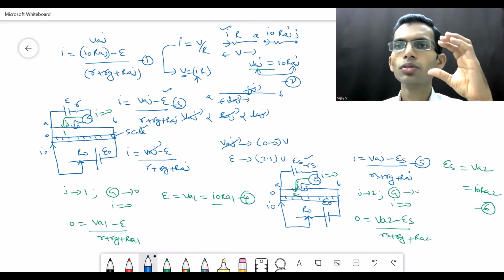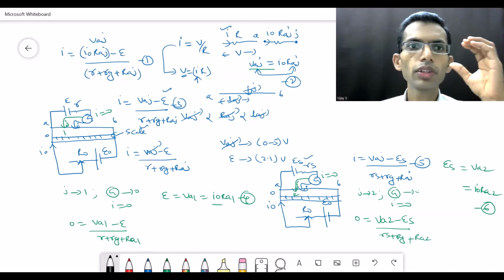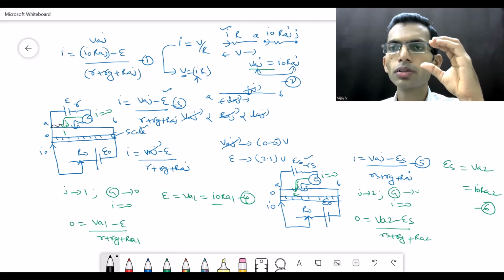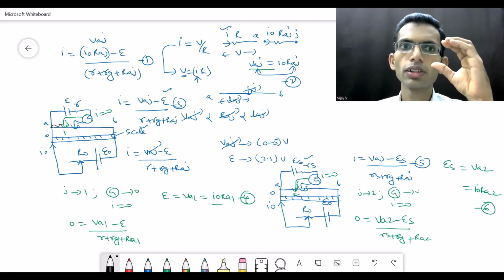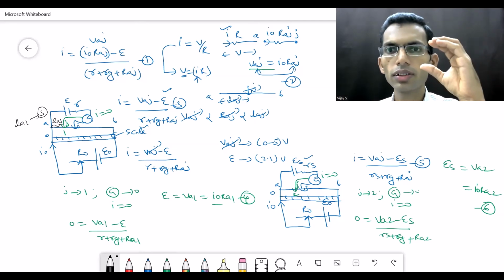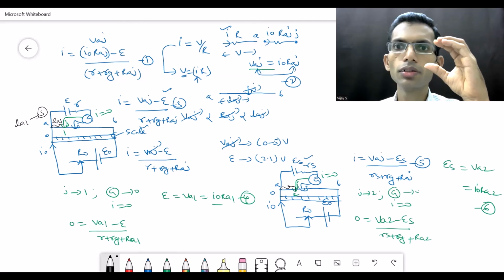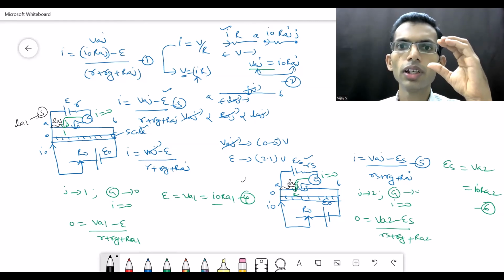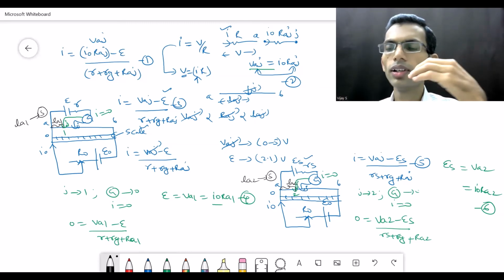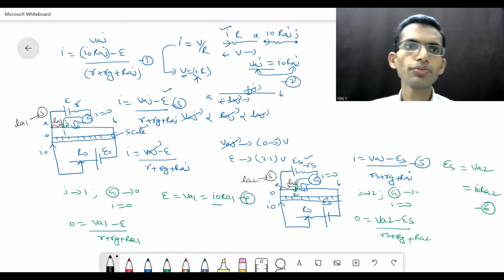To measure the length of the wire between junction A and the moving contact position for which the galvanometer shows zero deflection, in the first case LA1 we are going to measure with the help of the scale. Here also in this case, LA2 we measure with the help of the scale, which has to be used in the next part. Let me move to the next whiteboard.